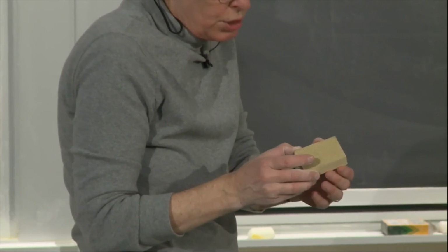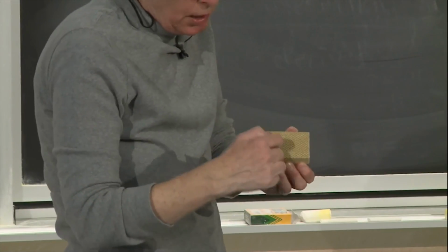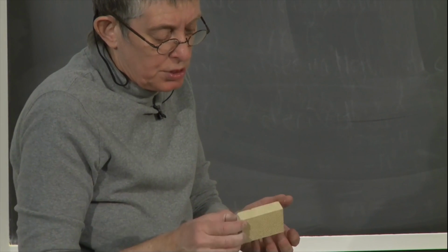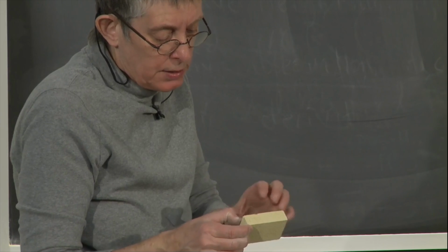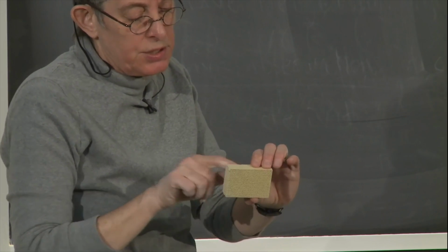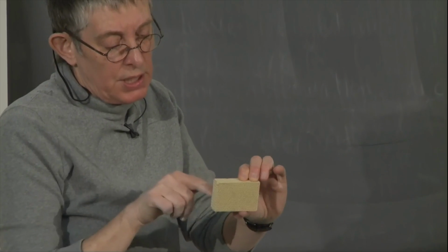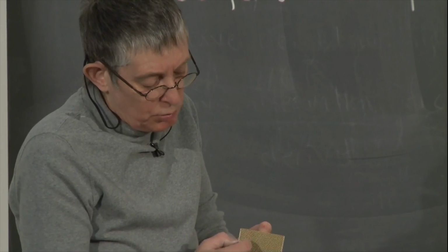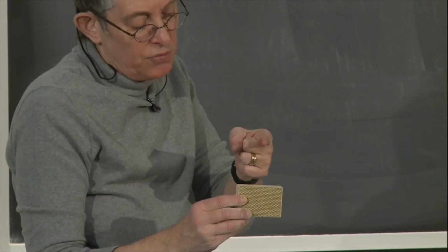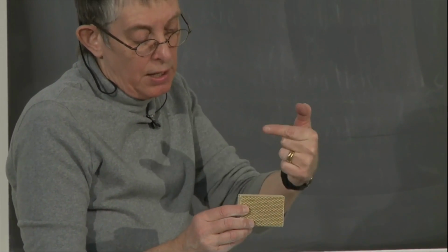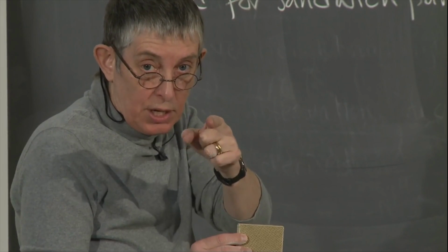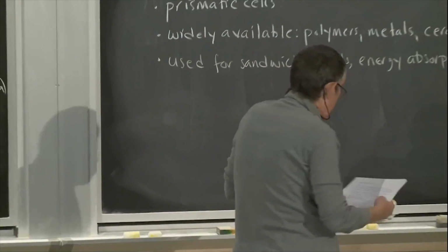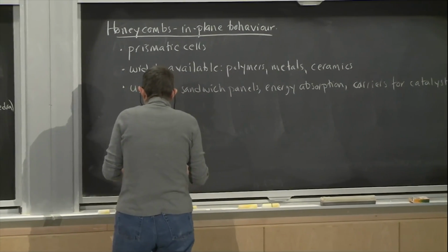The way that works is the cell walls here are actually porous, and they're coated in platinum, which is the catalyst. Half of the cells are blocked off on this end, so every other cell on this end is blocked off, and then every other cell over here, the opposite ones, are blocked off. So the gas is forced down a channel, then through the wall and out the next channel. That's where the reaction actually occurs, in the cell wall. So they're used as carriers there.